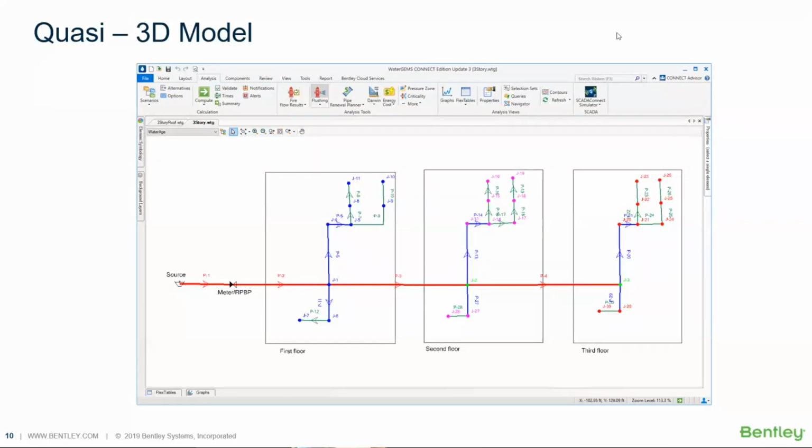So you can do some tricks, though, as I showed in the talk I gave about a year ago in one of these sessions, where you can take them and lay out each floor with the plumbing in it and do simulations of it. You take each floor and you couple them by the riser pipe going up through the building.